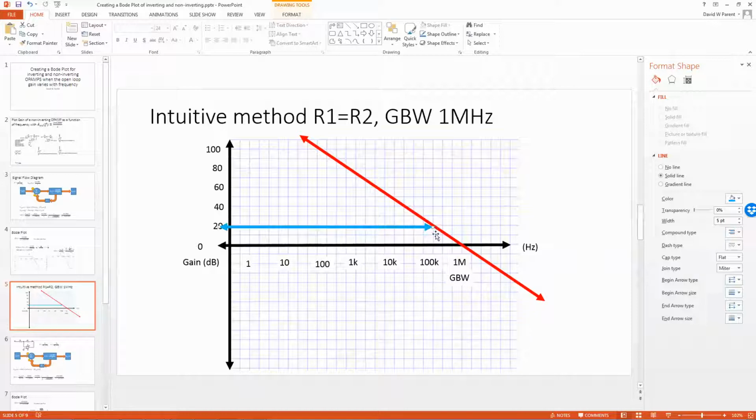And just so you know, omega naught depends on beta, which is the voltage division of these resistors. As the gain goes up, beta goes down, and omega naught of the amplifier goes down. And so if I want a gain of 100, I'll come here on blue, come down red, and that'd be my Bode plot.